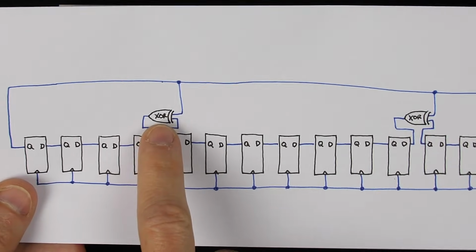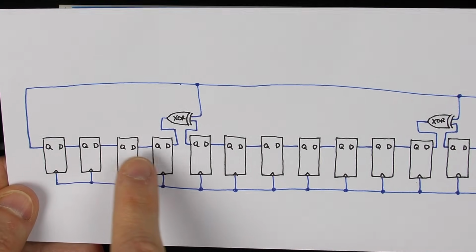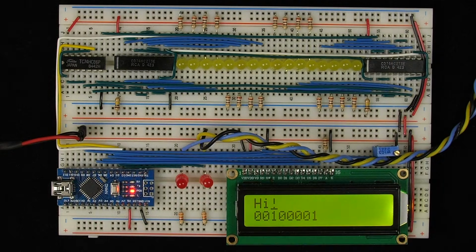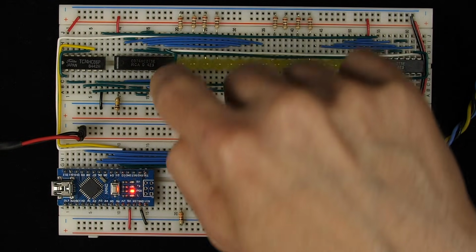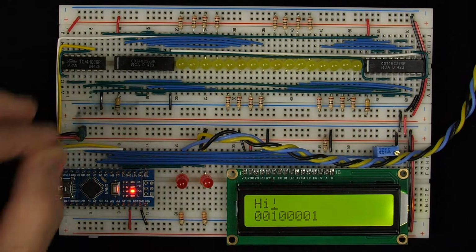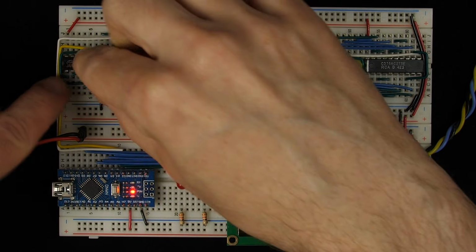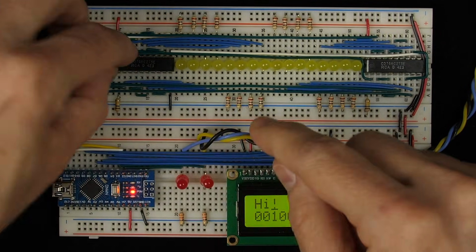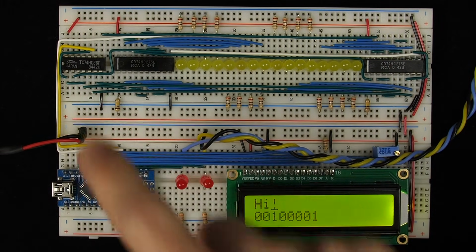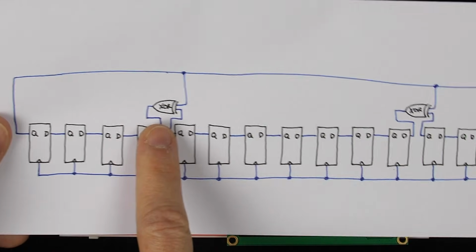So then we now need to insert this XOR gate, which is probably going to be easiest to count from this side. So 1, 2, 3, 4, and 5. So it's between the 4th and 5th from this side, which is actually just going to be, there's 4 on each side of this, so it's going to be this jumper that's jumping from one side to the other. So I pull that jumper out. And so now the output up here is going to come down into one of the inputs of our XOR gate. So pin 1 I'm already using, so we'll use pin 2 as the second input for that XOR gate. And then the output of that XOR gate will be pin 3. And so pin 3 then comes around to the input down here. And so now I've inserted that third XOR gate.